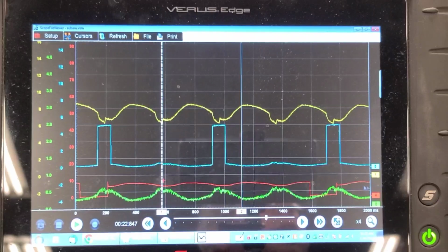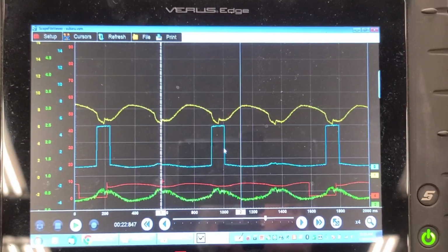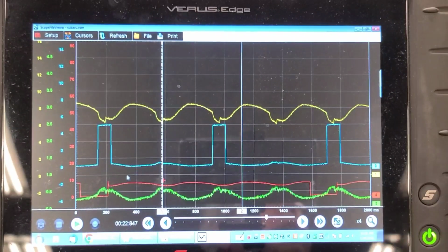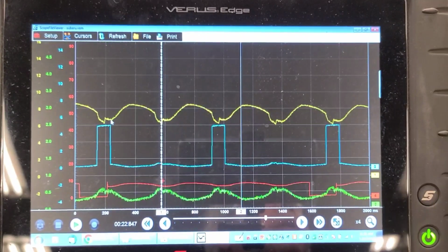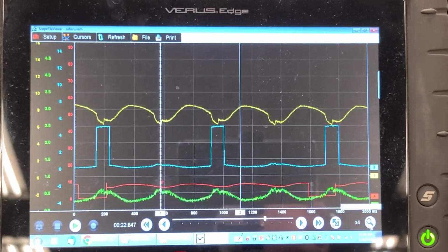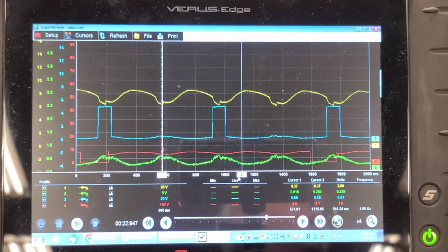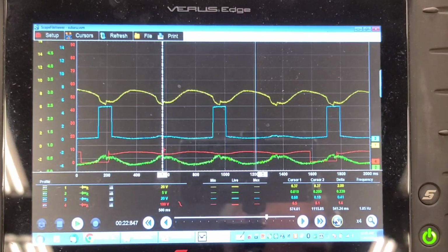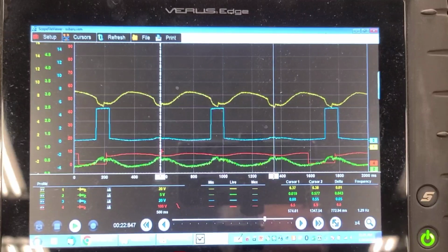So here's the recording. You can see that we've got an ignition reference pulse to number 1 and 2 coil. That's the blue trace. We've got injector firing event, but the system voltage is so low under cranking event. Let's drop cursors on here. Where cursor number 1 or number 2 is, the voltage to the ignition coil dropped to 6 volts. That's not enough. I mean, it is 25 below, but still it should make some attempt to fire.